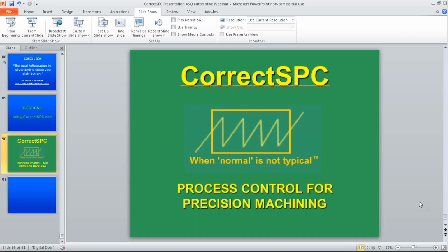Another question is about the example shown, referring to the 50-point samples, which use spec limits as the reaction points, so to speak. What was meant that they didn't calculate the control limits properly? Actually, for the X-high-low R chart, we use 75% of the specification as the control limits. Again, sometimes you need to adjust that depending on your process, but that's a good starting point.